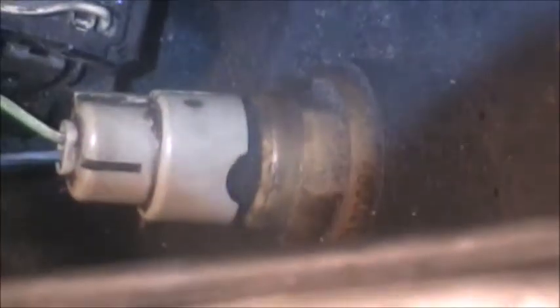Alright. Now if you look down here, there's the output speed sensor plug right there. And I have the insulation peeled back because I'm going to do some testing there. I'm going to find out if the sensor is bad. Now these sensors are known for going bad, but also what's known for going bad is right where the wires go into that plug, they go bad. Now a lot of times you can do a wiggle test and you can get it to work. So let's see, I'm going to try to do that.